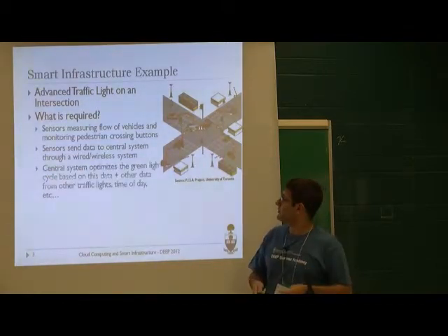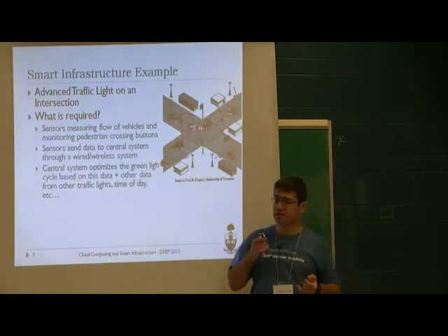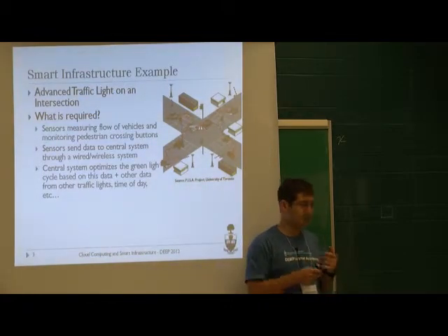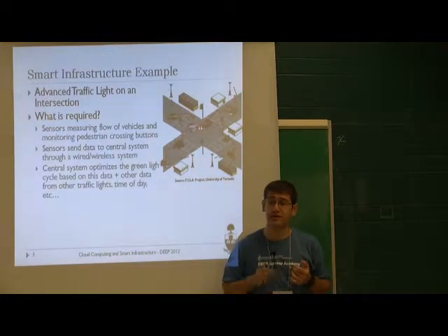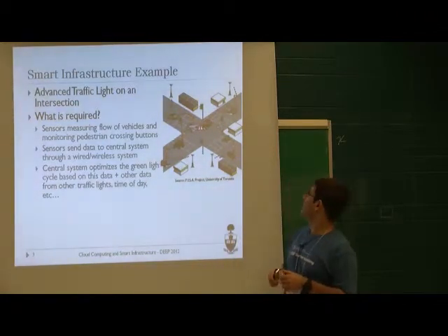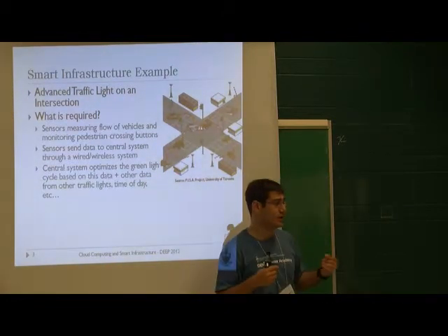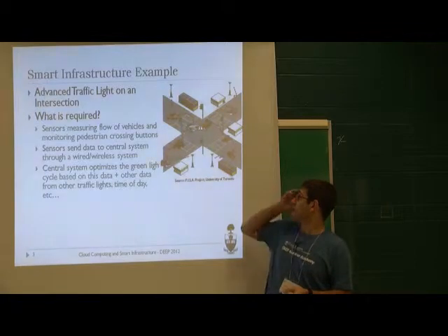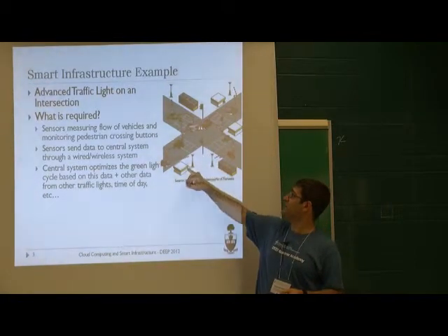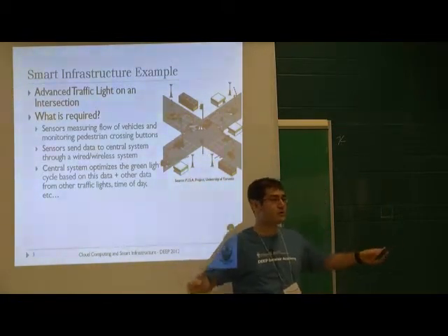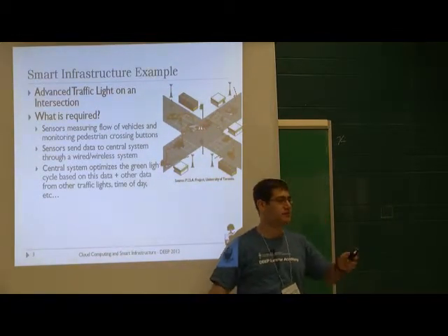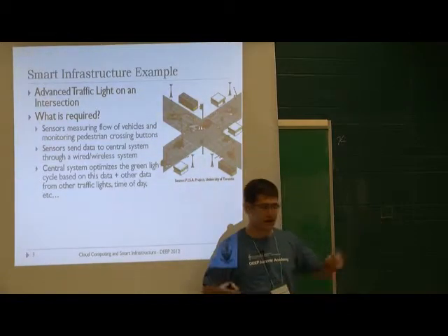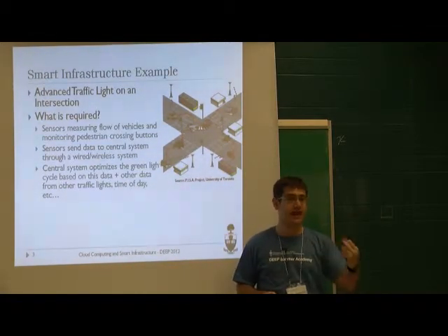Okay. So it will optimize the data that is coming from here. Another thing is that it will also use the vehicles that are coming. An interesting thing that I didn't know a few years ago, and I now test it when I'm on a local road, is that before the intersection, depending on how wide the intersection is, it could be something like 10 feet to maybe 15, 20 feet, depending on how big it is, you have a detector there.